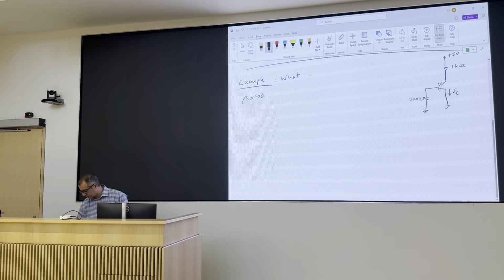But if you don't have that limitation, if you're using a benchtop power supply, or it's none of your concern, somebody else has to worry about it, you don't go below 0 across the base collector. So if base collector is 0, again, I say that's the edge of saturation. I don't forward bias like that at all, if I can. So at that region, if that's 0 and this is 0.7, your VC is about 0.7 volts. I don't make it less than that, if I can. If I really, really have to, maybe I can lower it to about 0.3, 0.4 volts. But after that, you're going to see distortion. Okay, so that's saturation, right?